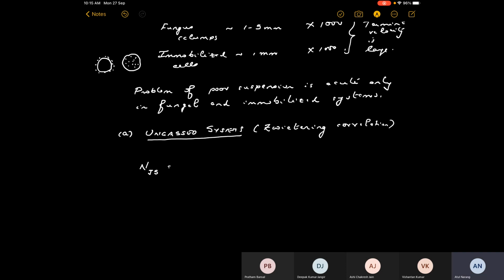He said that it is always a function of, first of all, this function S, which I'll give in a minute, of impeller type and di, the ratio of the impeller diameter to the tank diameter, and the off-bottom clearance of the impeller, divided by this, and then multiplied by nu L, which is the kinematic viscosity, which I will define more clearly in a minute.